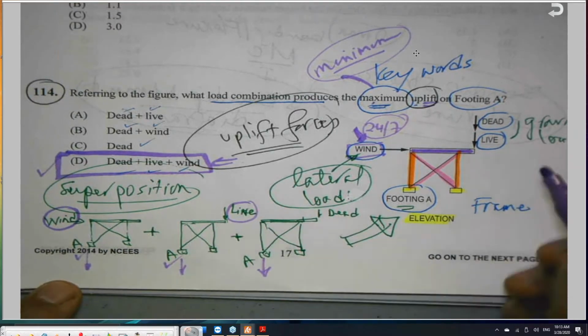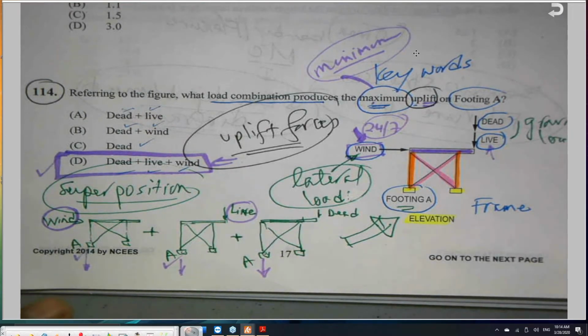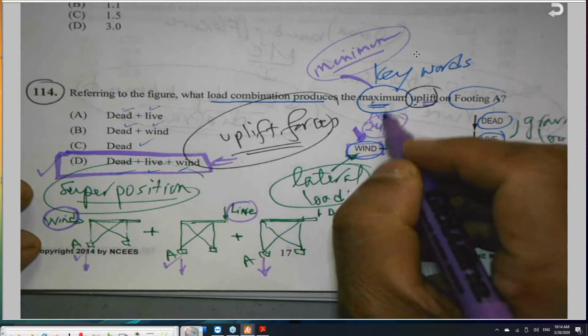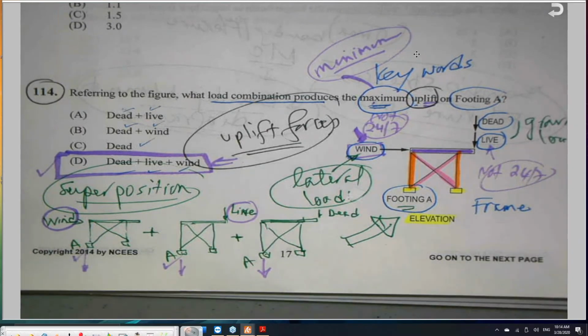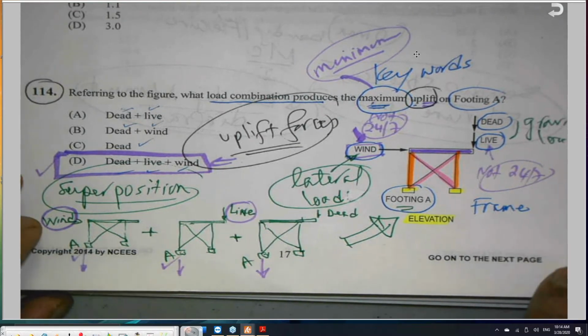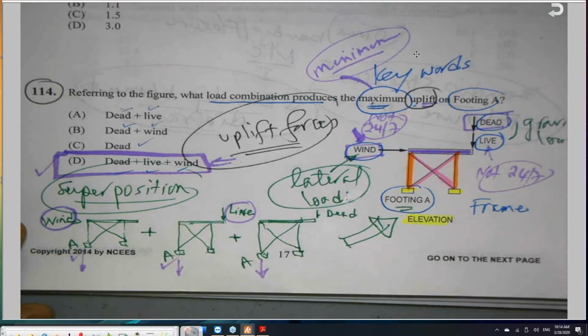Okay, this live load here, is it a live load on the structure 24/7? No, it's a live load like me and you. We are occupying a building, and nowadays most of the buildings are empty, okay, because of this crisis. But the live load is not 24/7. At midnight, even without the coronavirus, some businesses have nobody there except very, very few. Security maybe, or somebody taking care of the building, but they are not 24/7. But the dead is always there because it's dead.